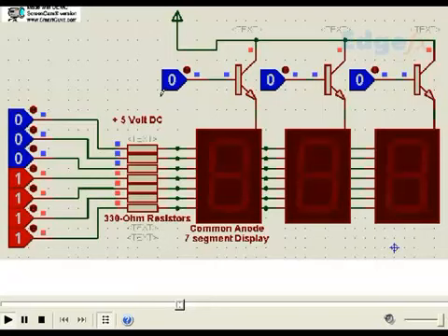So exactly what we do is, for example, when the digit 7 data is coming from the microcontroller in this fashion, 0, 0, 0 and 1, 1, 1, 1, in that particular event, this is given high. Now supposing the next digit that has to come from the microcontroller is, say, 1 and 1, 0, 0, means you will get 1 and 1. That time this will be switched on. That means this will go logic high. 0, 1, 0.